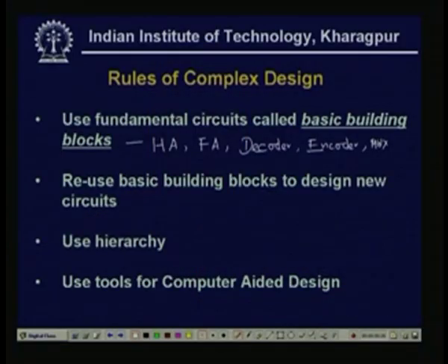Now, use a hierarchy, the concept of hierarchical design. As an example of such hierarchical design, last day we saw a larger multiplexer designed from smaller multiplexers. We call this a multiplexer tree.